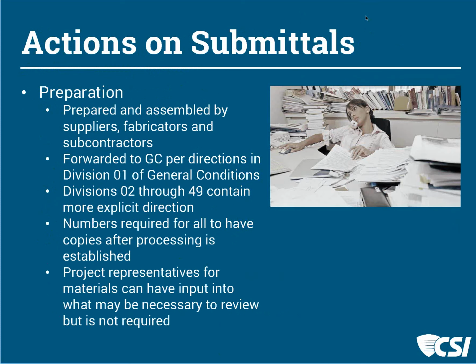So the submittal is going to come from a fabricator, a subcontractor, a supplier, and go through the contractor, the general contractor. Typically, the description of management of that submittal and preparation of it is in Division 1 of the general conditions. But within each division of a product, there's more explicit information about the preparation of the submittals themselves per product.